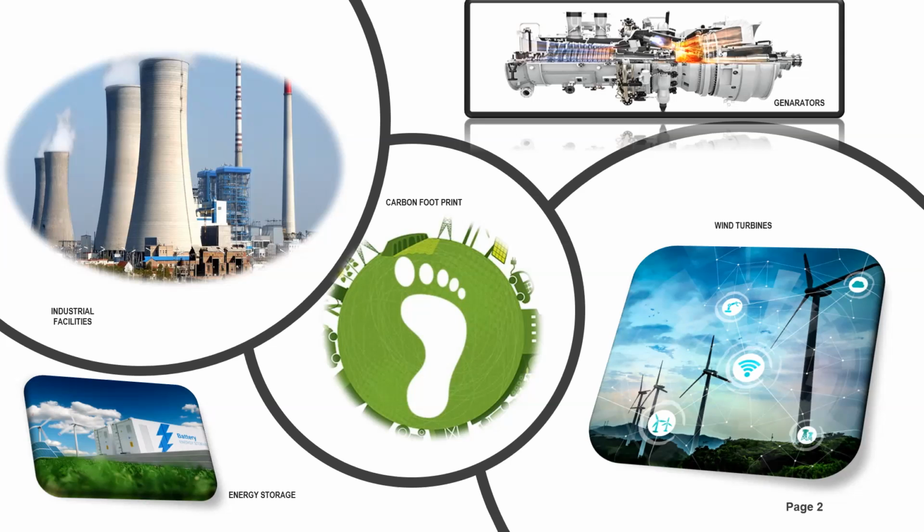Facilities with generation systems prefer an operating structure parallel with the electricity grid in order to ensure the continuity of their energy reliability in case of faults in their internal system. However, it is difficult to cope with long-term grid failures, and they must be isolated from the grid quickly and safely. The coupling systems are installed in order to meet these functional needs.